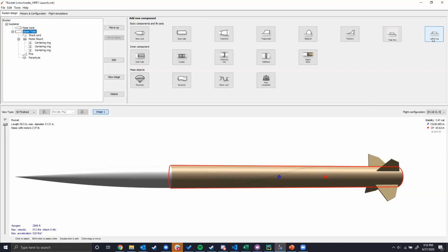For larger rockets, for high power rockets, you typically don't see launch rods. You typically see launch rails, the distinction being that launch rails are a lot more sturdy and are typically made out of aluminum extrusion. Rail buttons are basically a small button that's screwed onto the side of your rocket that slots into the slots on the launch rail. You'll want 2 of those. You can have 3, but there's typically not much of a reason to do that. Your best bet is to have 2 to make sure it's aligned well.